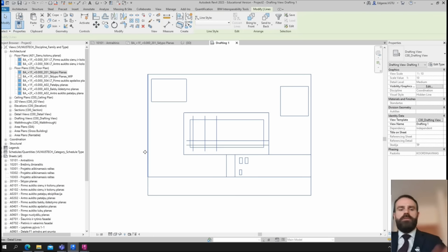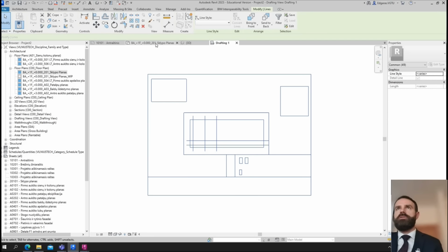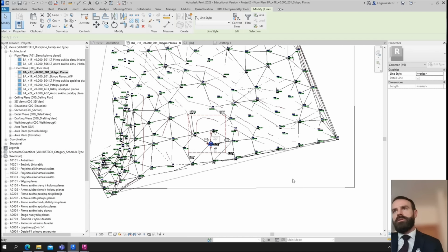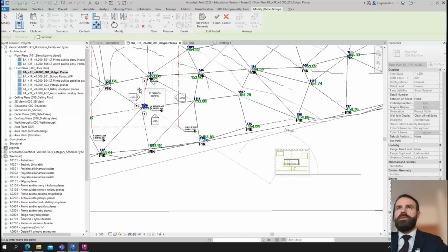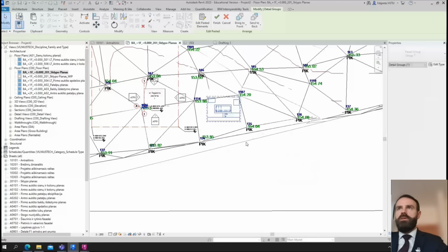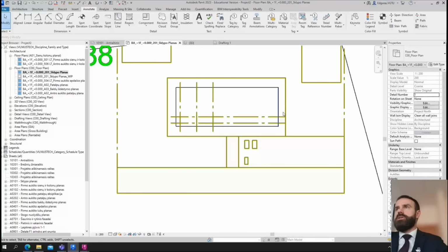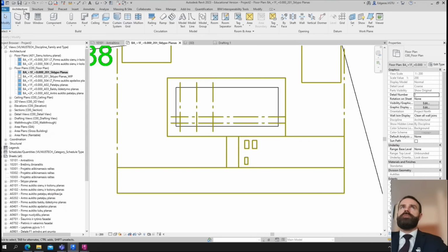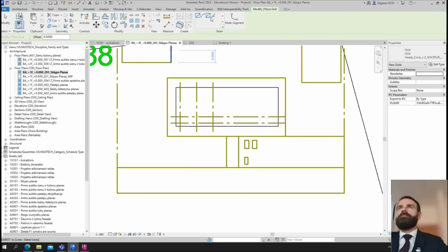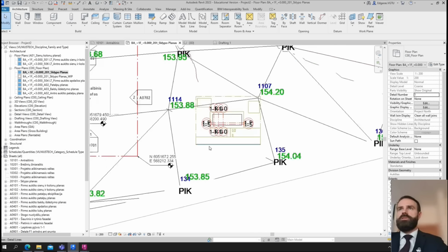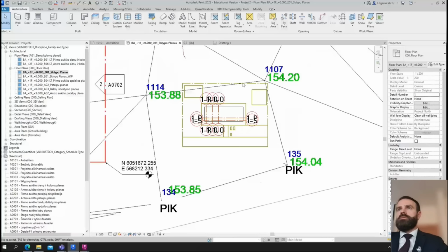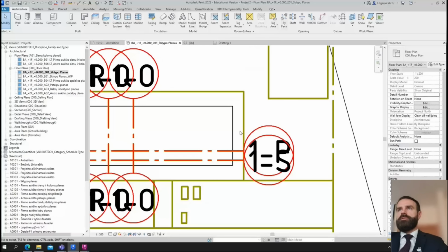So later I can select all this draft and click Control C, go to my property, Control V, and all this draft can be moved to the needed position. And all these dash line, grid lines can be converted to components from architecture tools. I need grid lines. I select converting tool, and here automatically I create grid lines from my project design. And now I have representation of lines of my buildings.